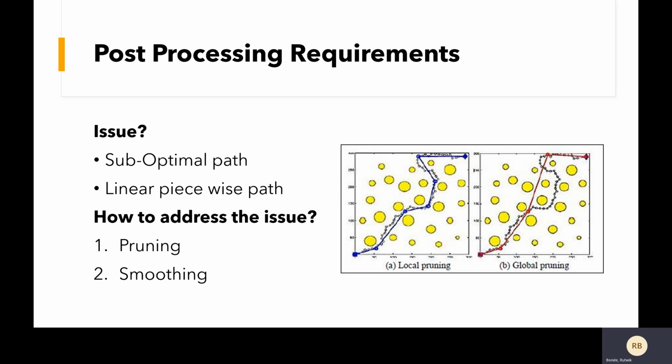But what happens is that even after pruning, the generated linear piecewise path is not feasible for UAVs and car-like robots. Curvature discontinuities in the path make the controller unstable and cause energy overshoots. This phenomenon can cause mechanical aging, localization errors, and high energy requirements. The situation becomes more complicated when the planning application involves heavy machinery such as industrial, defense, or agricultural robots.